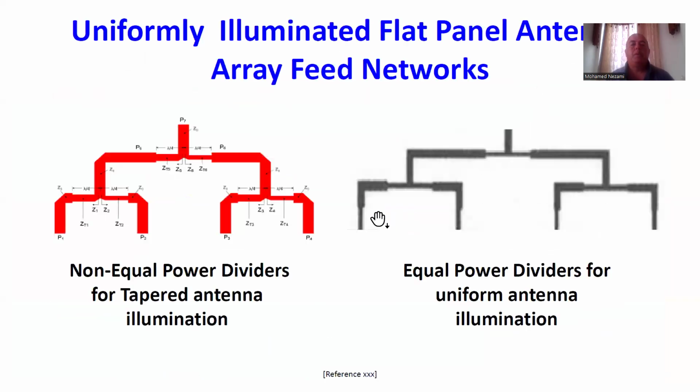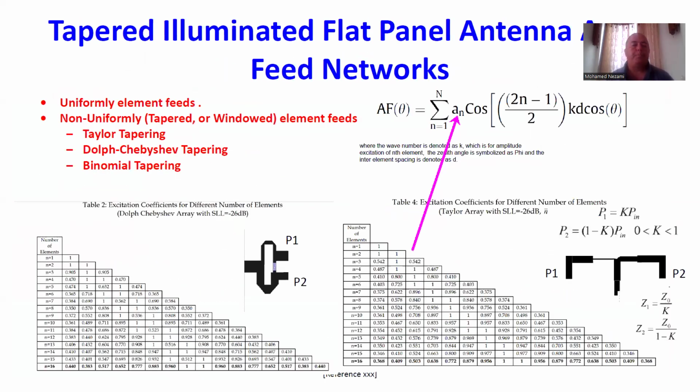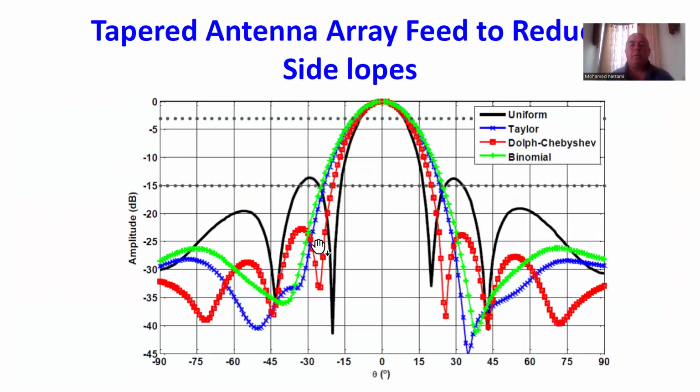Okay? So basically we showed that. So why do you do this? Why do you taper the values? Well, we taper the values, first of all, to reduce interference. So if you have an antenna that points this way, you definitely don't want side lobes that are only 16 dB below the main power. That's a lot of power to radiate adjacently on both sides, and it's all symmetrical, of course.